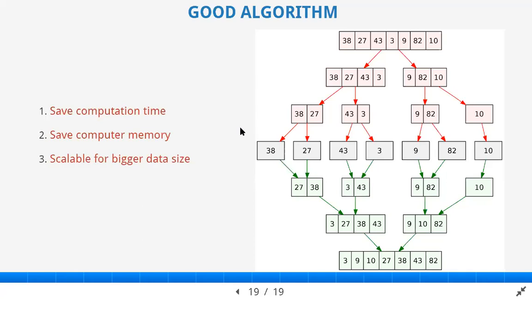That's why we have instruments to test our adhesive joint. We have a tensile test, and in our laboratory we have the split Hopkinson pressure bar test, which tests joints with impact load, and we compare with our model.